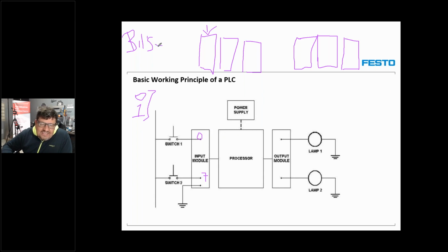Now, I always say to the guys, this is a rule. The first bit is also your byte address. That means when you start off with bit 0, then we get bit 1, 2, 3, 4, 5 until 7. Okay, guys? Then a byte 0, and then you get byte 1, byte 2, byte 3, and we can go on. It depends on the performance capabilities of your PLC. How many inputs can be wired? What is your PII? And I'm going to explain that to you now.